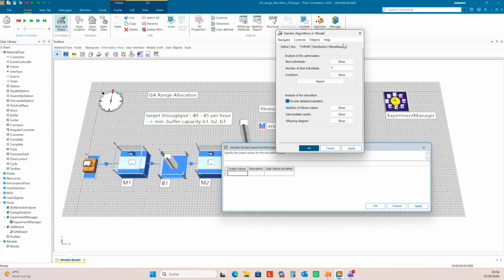But I had such cases here from students: if you don't have differences between the simulation runs, then it finishes quite fast, and it doesn't run the optimization to the end. So it just stops if we don't find differences between the simulation runs.